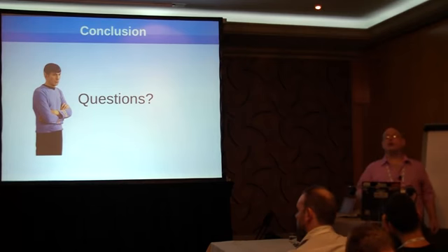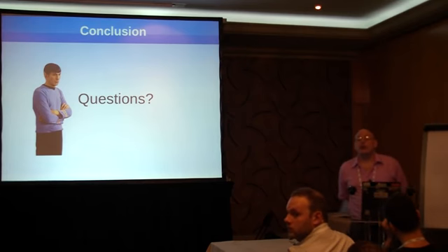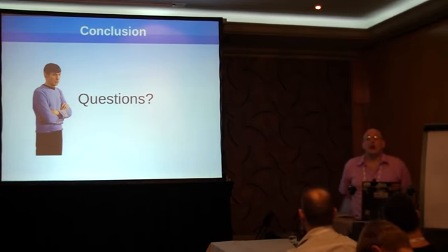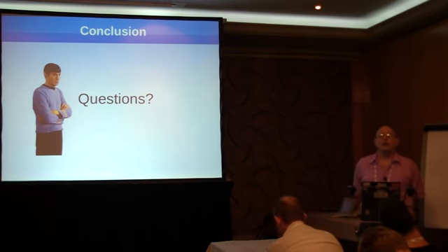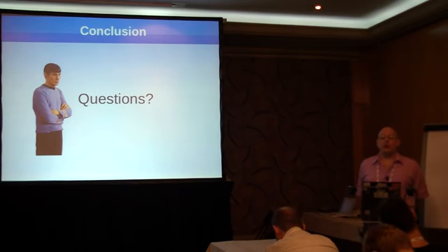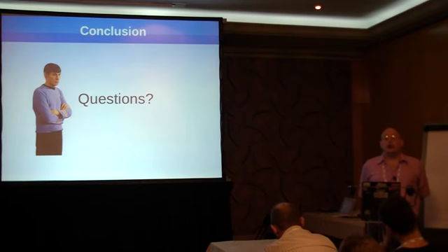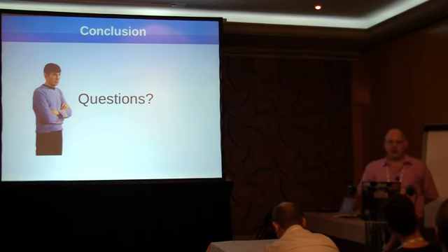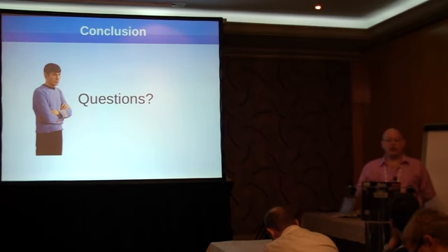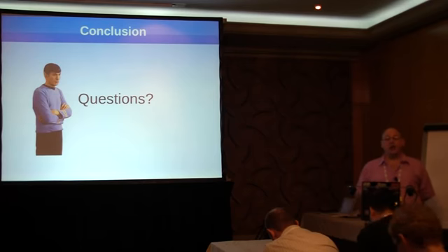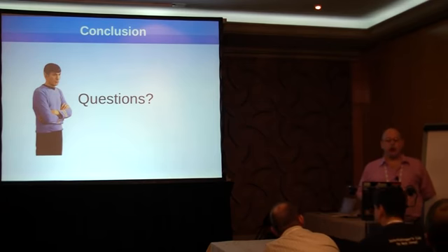Say when you've got a dead board, what sort of external device do you use to read the I2C bus on there? I'm sorry, can you repeat? Say you've got a board that's died, and you want to read the EEPROM on that board, so you have to connect an external, say, USB to I2C device. What particular models have you used? The question is, based on my reference there about using EEPROMs for board bring-up, if the board has failed, how do you read the EEPROM on your host PC or another target?